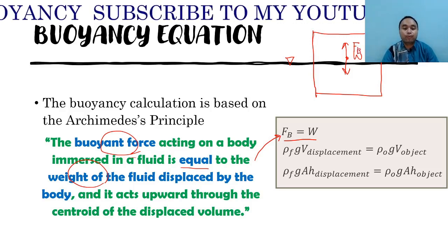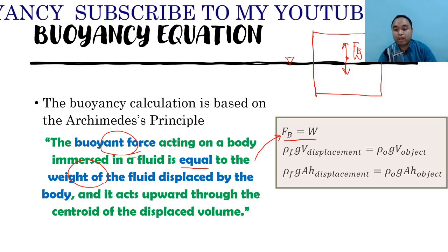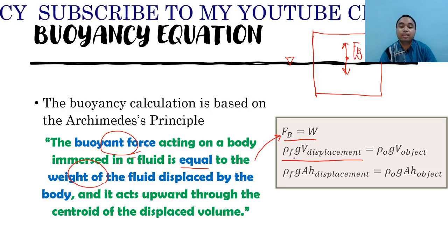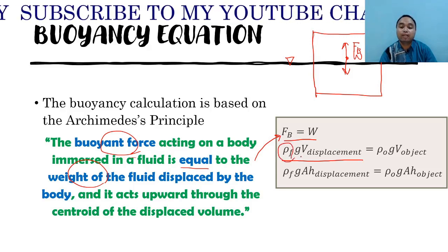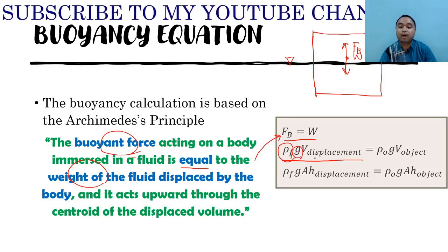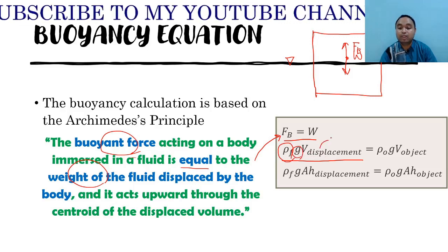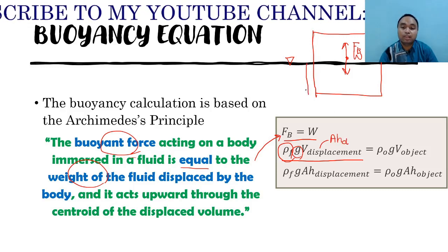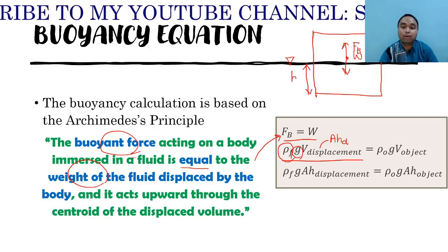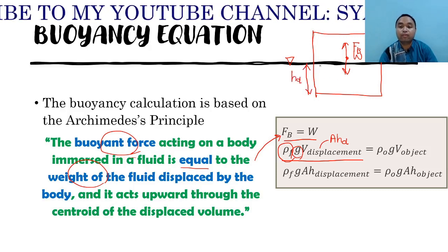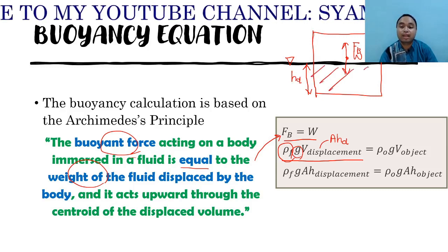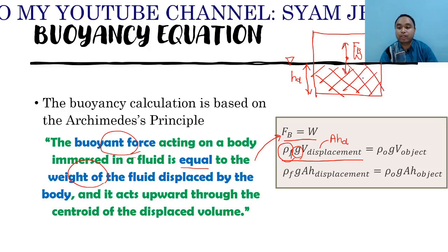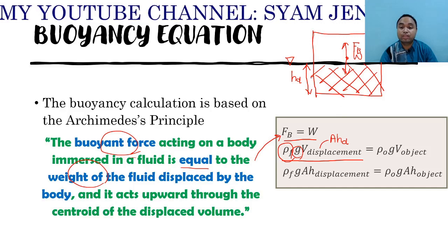Okay, in order for us to do the calculation, we have to give the definition of FB. The definition is the density of fluid multiplied by the gravitational acceleration multiplied by V displacement. So what is V displacement? It's actually area times H displacement, and H displacement is the height of the body which is submerged inside the liquid. For this particular body, this part that I have over here is submerged inside the liquid. So this is your HD.